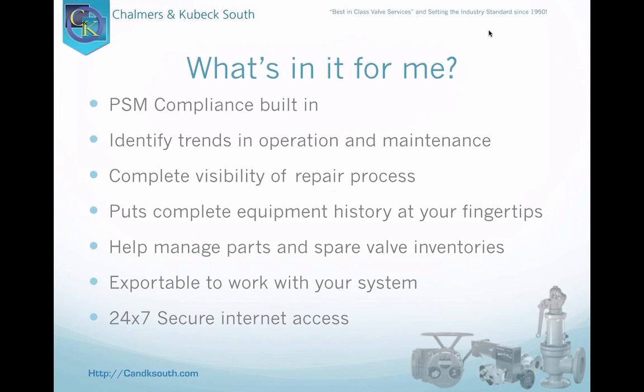Where it comes to other pieces of equipment like an MOV, Limitorques have a limit switch in there that has a range of torque that it can output, and it's basically set up that way when the actuator is sized to the equipment that's going on. And it's designed to give you more torque over time as your valve starts to wear and get increased friction, those kind of things. However, when you start to see that creep over a history of a valve, it doesn't necessarily mean to do more PM on the actuator, but it definitely indicates you need some work on the valve. So whether it be safety valves, actuators, or anything we're working on, there's data in there that can help you with identifying trends so that you can determine what you need to do as far as maintenance and maintaining that at the lowest cost possible, of course.